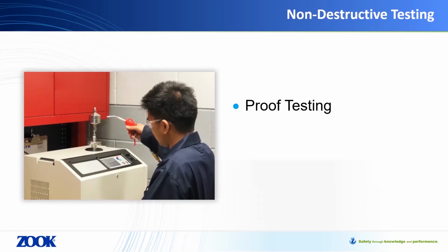As many welded products become an integral part of the piping system, it is critical when mandated by code, by a customer, or engineering authority to perform such testing on welded joints. Earlier, I had mentioned that leak testing is one of the major value adds when it comes to a welded product. With the use of in-house leak testing equipment, rupture disc engineers have the ability to validate not only some, but all of the components, and if required, provide exact leak rates for each unit supplied within a batch. When leak tightness is critical, this is a must-have requirement.